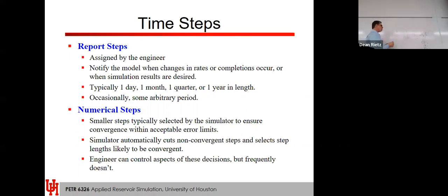Now every once in a while, it'll come to a place where, remember, we're telling it this, and we want output then. You have a whole bunch of control on the output. You could have it print to the print file. You could have it exported to a separate file where, if you want to look at saturations through time and stuff like this, you'll have this information in there. So you could look at these pretty plots with the saturations moving through time. Let's say you want to know oil saturation or pressure or porosity, which does change through time sometimes, you can have that output, and if you wanted to see it in the 3D displays, it will save a value of porosity for every grid block. So if you have 500,000 grid blocks, you'll have 500,000 values.